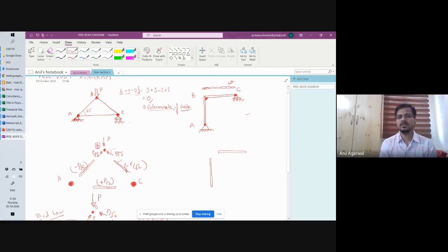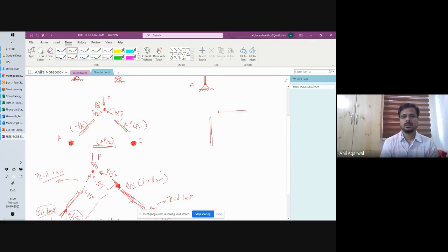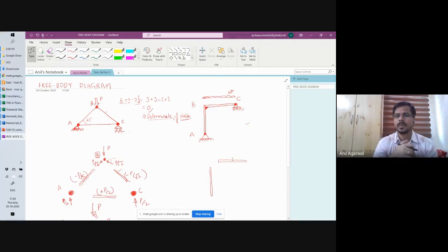So when I'm marking these forces, these are compressive and tensile forces, and my sign convention is plus minus accordingly. Positive for tension, negative for compression. And these forces, when I was showing the joint forces, those are just the external forces individually. These individual forces or these reactions. So these are P by 2 this way and P by 2 this way. Fine. A very simple system. I didn't pick a very complicated system to solve, just to elaborate. Any questions from this part?